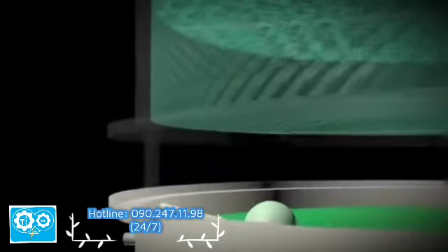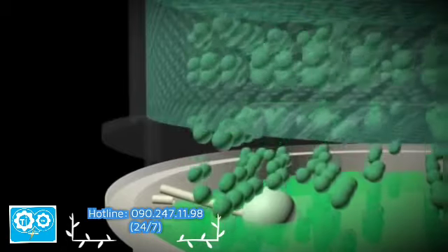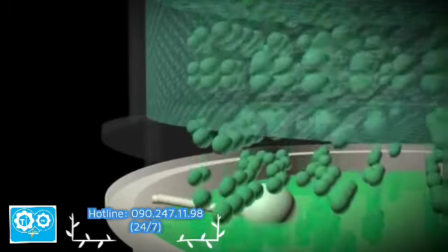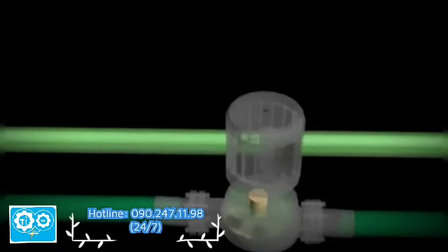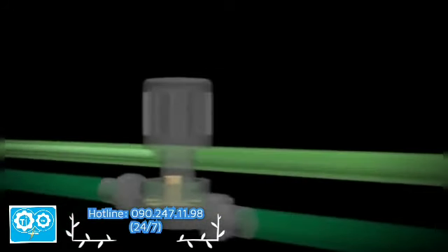The buoy system at the water basin is connected to the make-up water tank. It works for adding water when the water level in the basin decreases to a certain level due to evaporation. This condenser water cycle will continuously flow as long as the centrifugal pump is in good working condition.